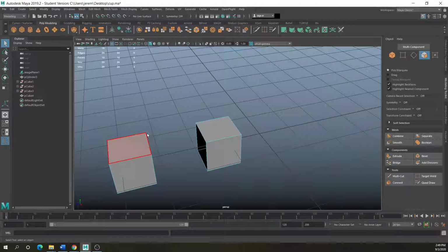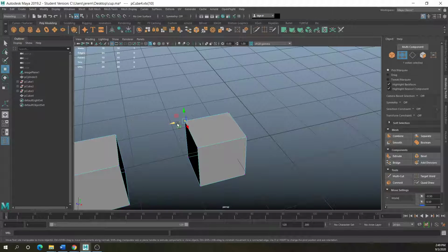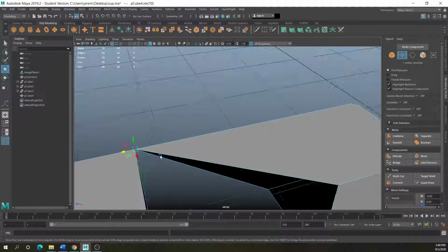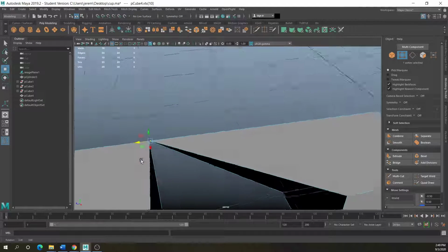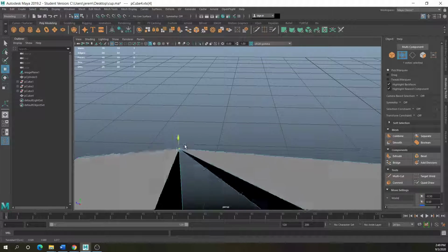You can basically take this vertex and this vertex and connect them. You want to go to vertex mode, you can go to move. Just because you move the vertex over, it doesn't mean that there's not two vertexes there, which will be problematic. So you really need to weld these together. You can just select both of them, shift and right click, merge vertexes to center, and it merges them together. So now you have one vertex.